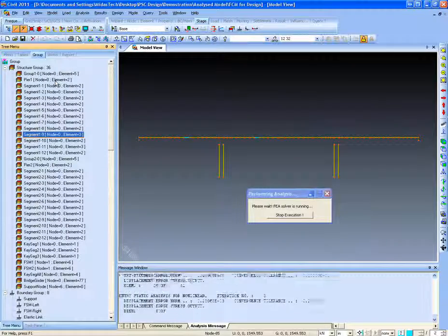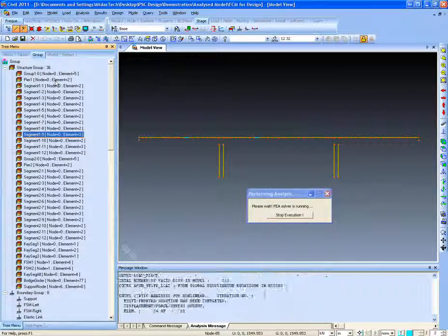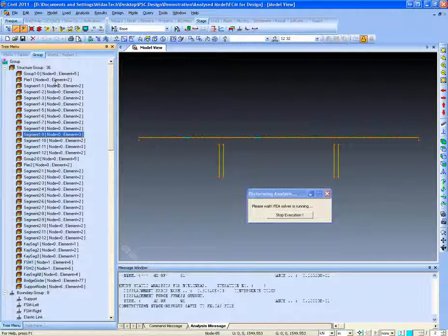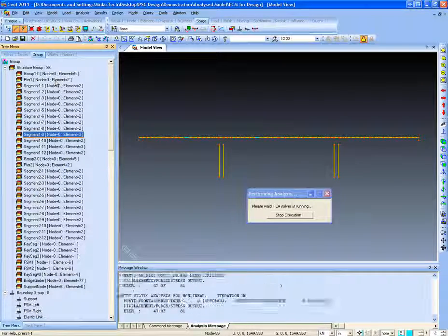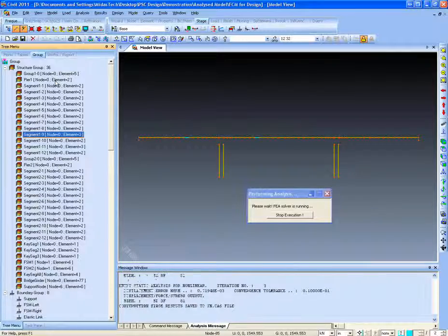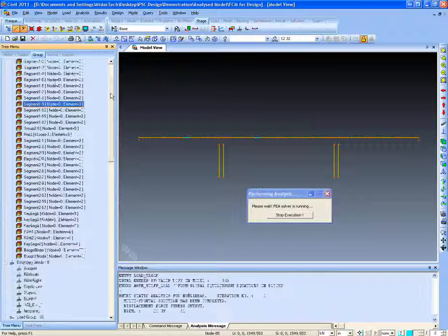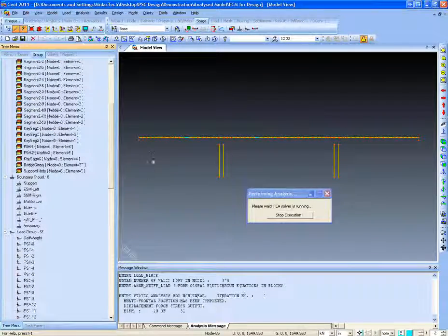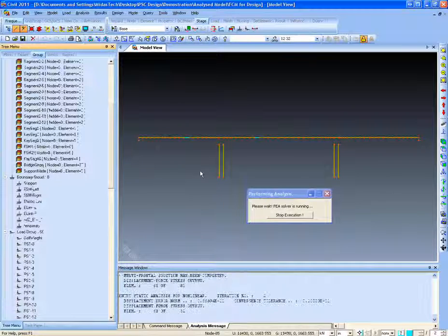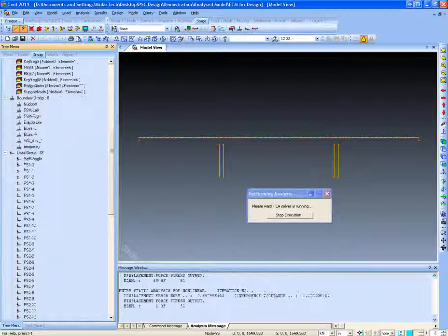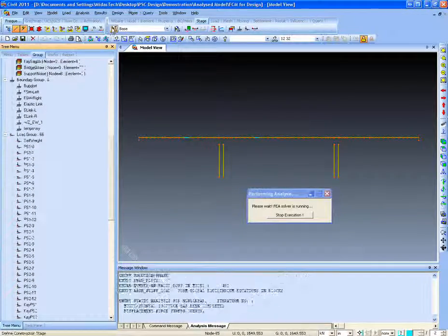And when the segments are constructed in actual practice, or the segments are activated, that means let's say we have the cast in situ FCM construction type of bridge, then we can model the dead load of the segment that has wet concrete still in our structure using the nodal loads, and when it adds to the stiffness of the structure, we can activate it. So first we need to define the groups, and accordingly we define the boundary groups for the same. The boundaries can be activated or deactivated as desired. Also, the load groups can be defined and activated as required.